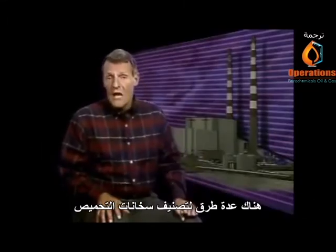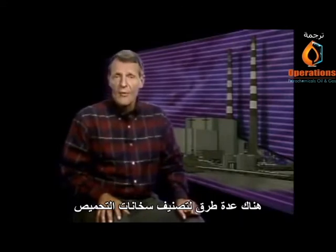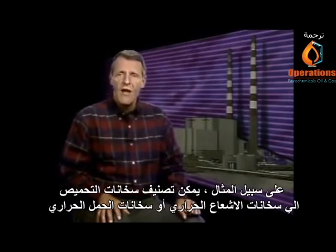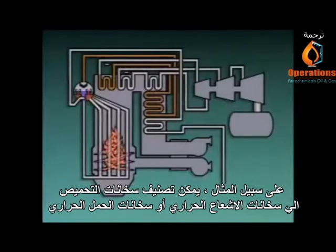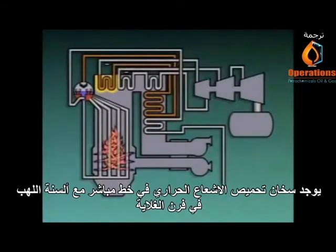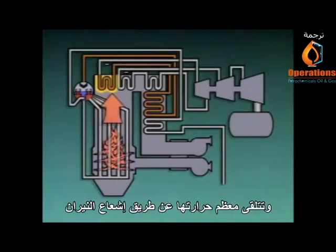There are several ways of classifying superheaters. For example, a superheater may be classified as a radiant superheater or a convection superheater. A radiant superheater is in a direct line of sight with the flames in the boiler furnace, and it receives most of its heat by radiation from the flames.